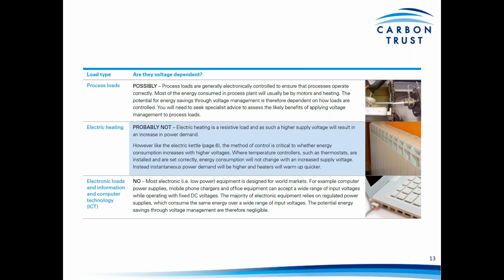So where temperature controllers like thermostats are installed and are set up correctly, the energy consumption shouldn't change with an increased supply voltage. What will happen here is that probably the instantaneous power demand will be higher, so the heaters will just warm up a little bit quicker.